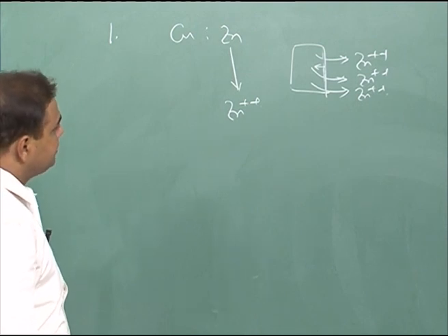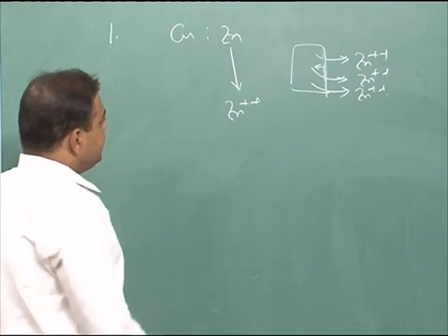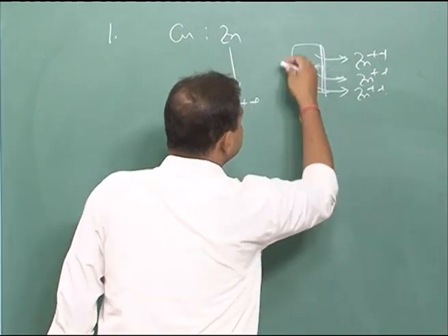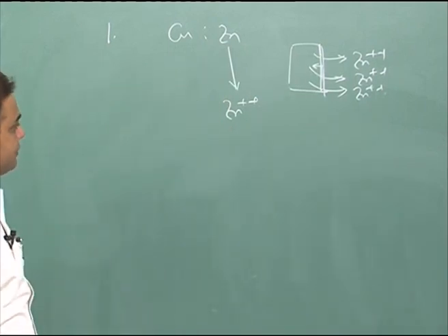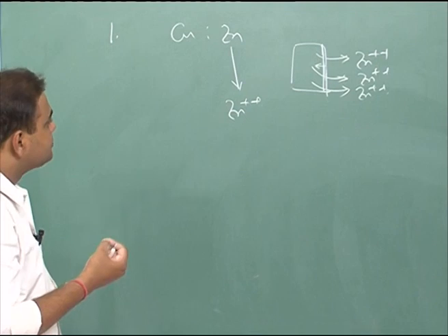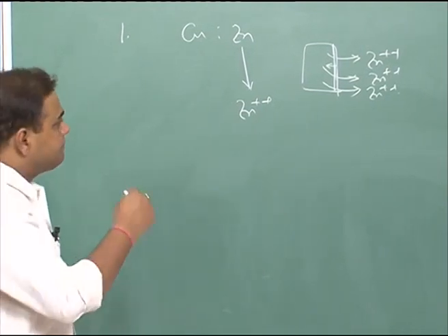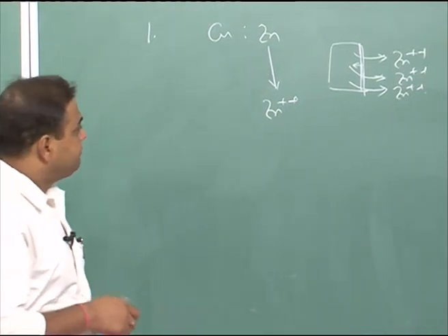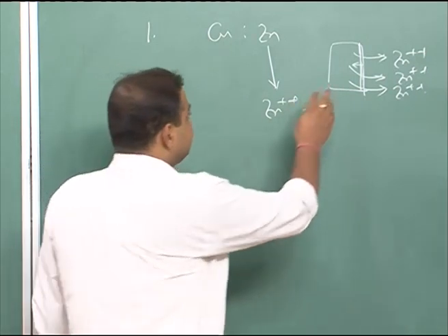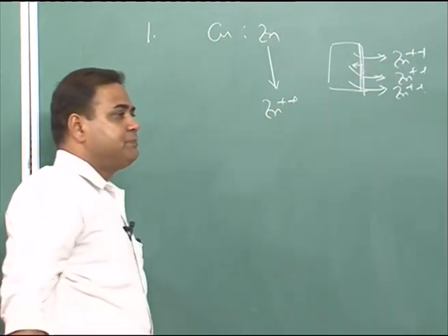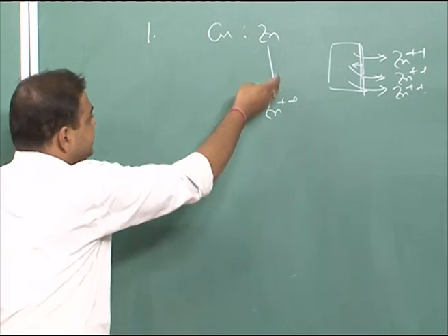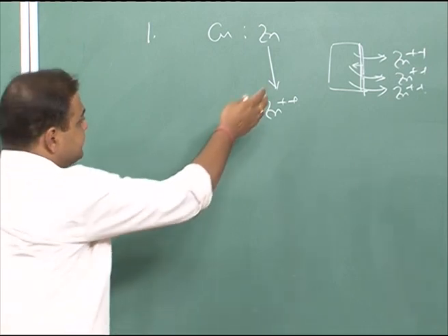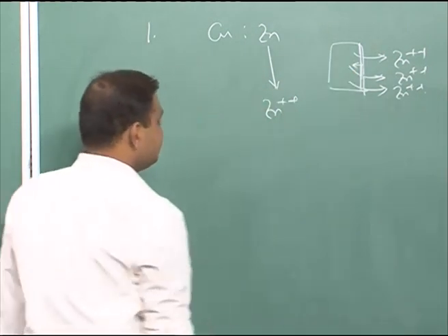Now, in this theory, the main problem is that the dezincification gradually grows in the depth direction, but the small pores that form need a solution supply through them, and that would be a little difficult. So the rate at which dezincification happens and the rate at which zinc dissolution should occur always do not match. So you have some confusion regarding this.